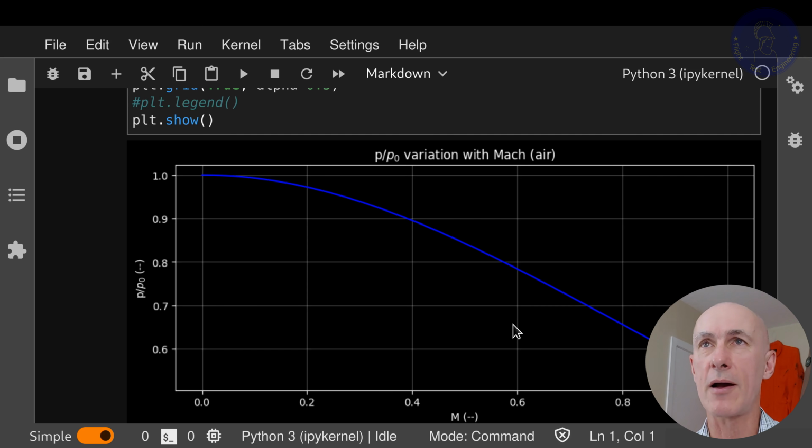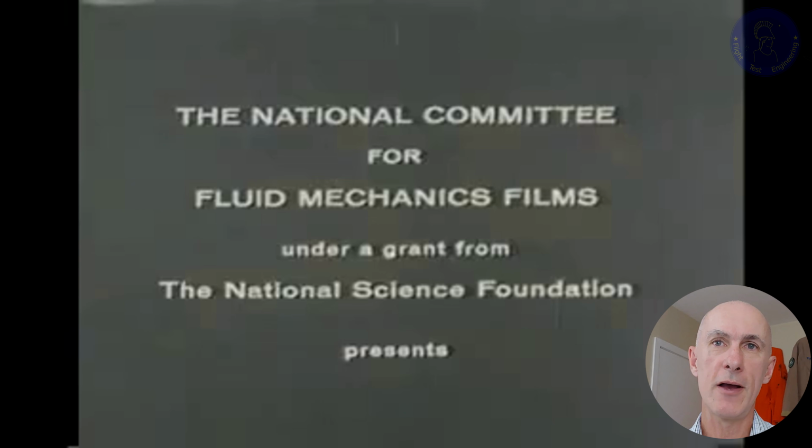Understanding this choking mechanism is key to jet engines because they generally operate in this condition, and if not at the nozzle, possibly at some passage in the compressor. To visualize all this, instead of showing you a simulation like I did, which is not physically accurate, I will show you instead the real deal.